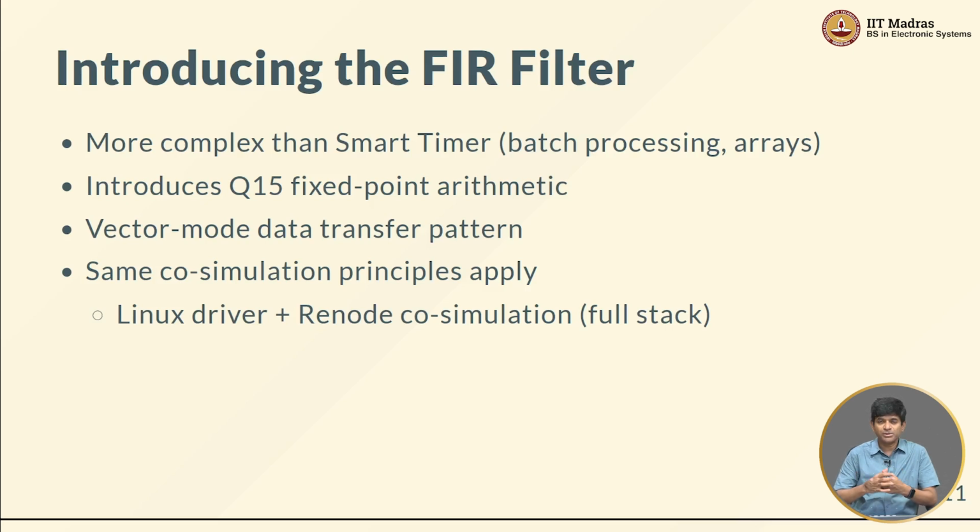Which is a finite impulse response filter, which is a common kind of peripheral that you might want to implement in hardware. It is one of those things which is very well suited to implementing on an FPGA, right? It has a large number of multiply accumulate operations that need to be performed, so it's just about perfect for an FPGA. It requires you to implement things using fixed point computation, which cannot be done very well in software. So all of those things need to be taken into account.